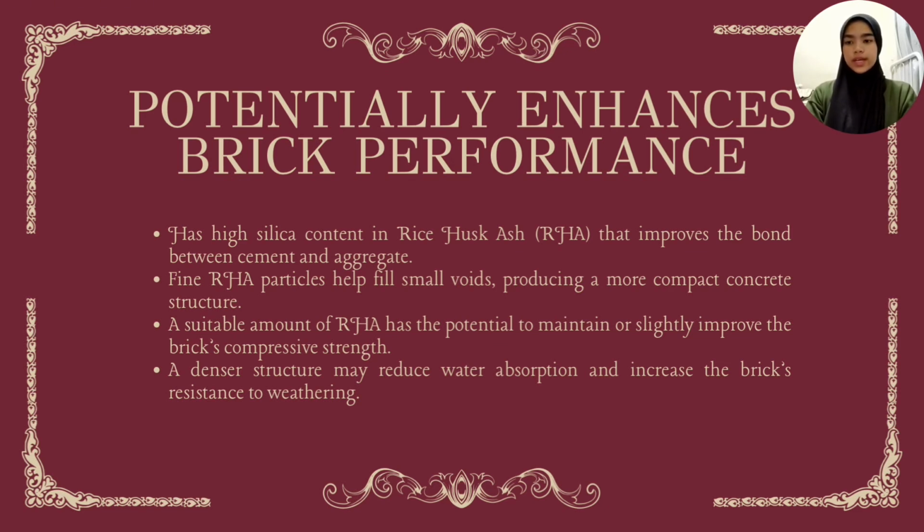For the last advantage of this project, we can understand that rice husk ash, or RHA, potentially enhances the brick performance in several ways. Its high silica content improves the bonding between the cement paste and aggregates, while its fine particles help fill small voids in the mix, creating a much denser and more compact brick structure. This improved density may help maintain or slightly increase compressive strength, and it also enhances durability by reducing water absorption and improving resistance to weathering over time.